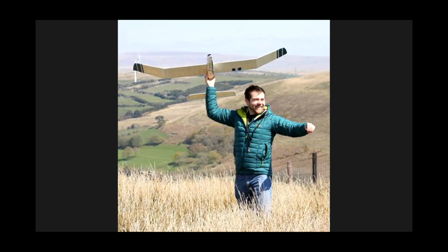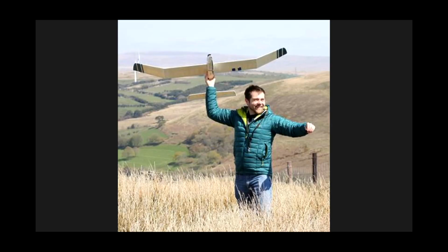Hey, Matt. So are you seeing much uptake in some of the other types of rotor head, like teetering rotor heads and articulated rotor heads in the ArduPilot community? Probably. I mean, you mean like teetering rotor heads that don't have dampeners in them? Yeah. Not a whole lot from the smaller sizes. I would imagine if you got to a larger one, like a Schweizer 333 or something that's a bigger, 1,000-pound helicopter, or maybe even 200 or 300 pound, they might have some rotor systems like that. But typically for the smaller helicopters, most of them use in some form a dampener that provides a stiffer rotor system. Okay.